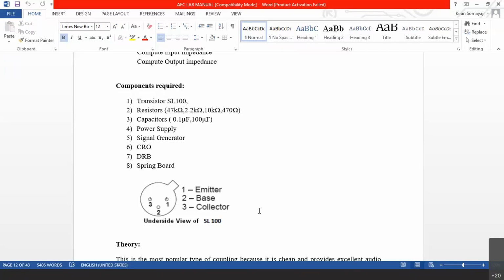You know that in case of an amplifier, the transistor works in the middle of the load line. That means the transistor is neither on nor off. So if the transistor is completely on, across the switch, ideally there is no voltage at all, because the switch is completely on.